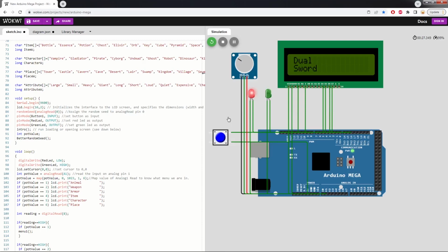Well, I think there's a glitch with the button, but that resistor would definitely help. Oh no, it's just that it's a push switch and not a momentary switch. So once you trigger it, it stays closed until you push it again. But that's not a problem.